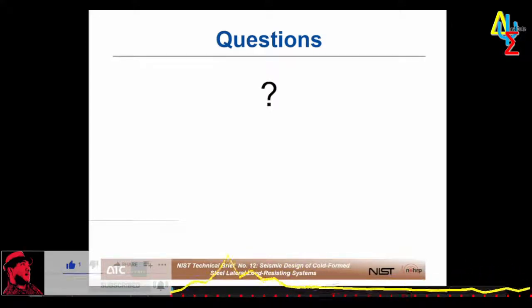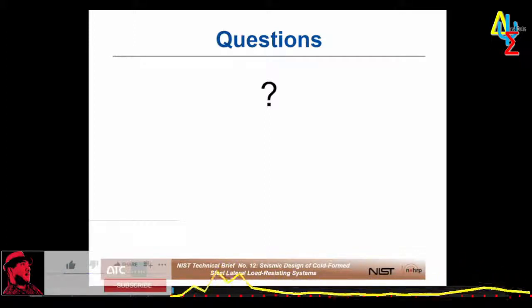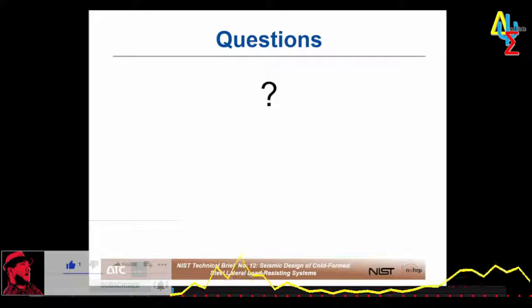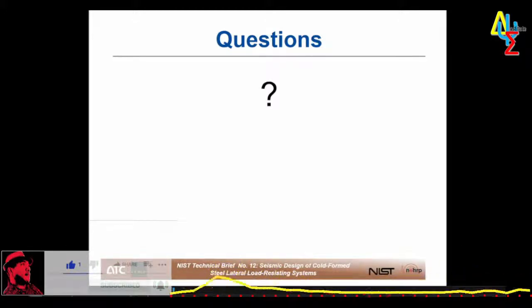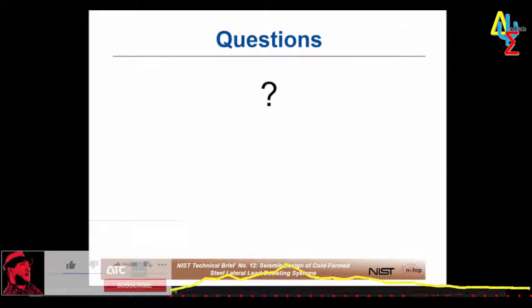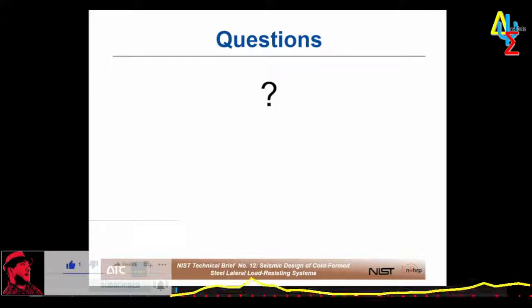Yeah, so I have seen a number of buildings that have used CMU shear walls at elevator and stair core areas. So, long skinny buildings that may have a core in the middle and on each end, for example, where the load bearing structure might be CFS and the core material was CMU. I've also seen very similar buildings, but with cast-in-place concrete cores. And from time to time I have seen buildings that are a hybrid, where, for example, the upper floors use CFS lateral force resisting system elements like a shear wall or a strap braced wall, but lower down in the building, they might be, say, a structural concentric braced frame or something like that.